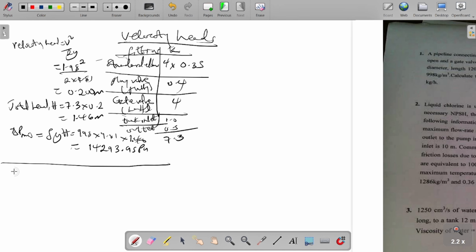So over here, we actually have to also calculate for the change in P for the pipe, right? For the pipeline, which is 8f L on D. So this L won't become L equivalent, because you're using velocity here, rho V squared divided by 2. Right? And here we know that 8 times the same friction factor 0.0258. Then the length was given as 120. That's the length of the pipe itself.